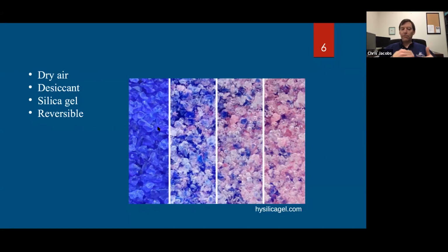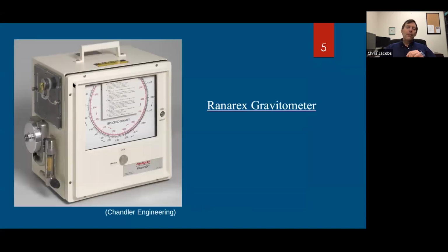So, it's continuously reusable. Now I'm going to go back. When you want to remove the desiccant from the machine, you remove these two thumb screws, and this whole plastic box will slide out of the machine. There's a hose behind it that's maybe 10 centimeters long, so it's flexible. You remove this plug, and you can just tilt this down this way.